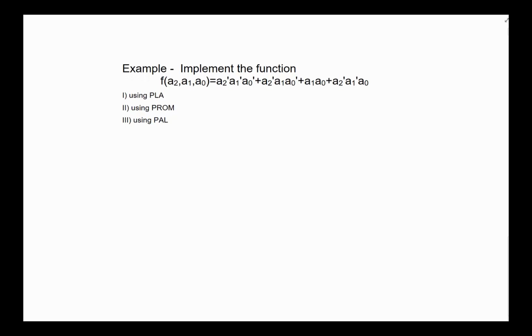So let's go ahead and take a look at an expression and see if we can implement it. We have this expression given. First of all, it's 3 inputs. When they say implement a function using PLA, what they're asking you to do is the fuse diagram for it. Once you've done the fuse diagram, that can be entered into the programmer device that comes with these things, and it will program it exactly like you want. So let's go ahead and take a look at it.